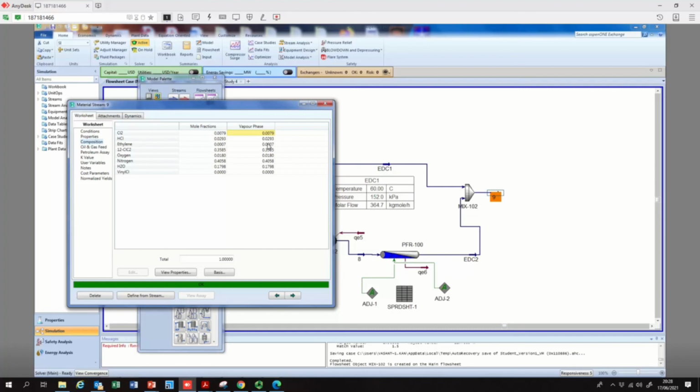But at 15 degrees centigrade, your air components and also hydrocarbons, this tiny gas which you see here in the vapor phase, will disappear in the vapor stream. That will give some level of purity. At least we will remove the air components and this ethylene. So let's add a small flash evaporator, like a flash column, and it will separate these components, hydrocarbons and some of the air products. Let's do that.